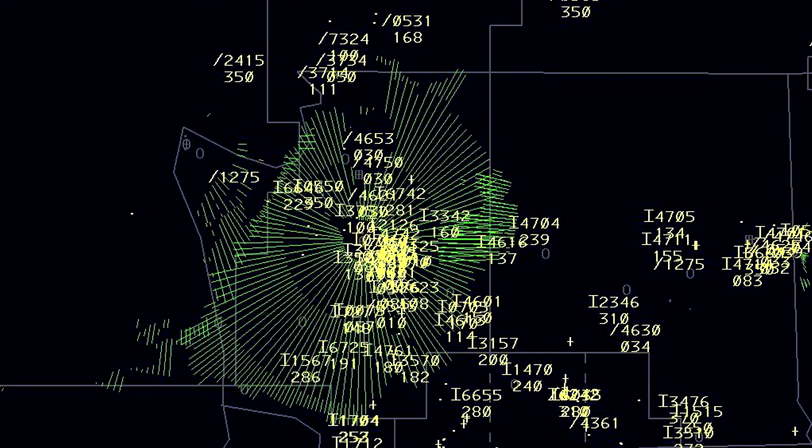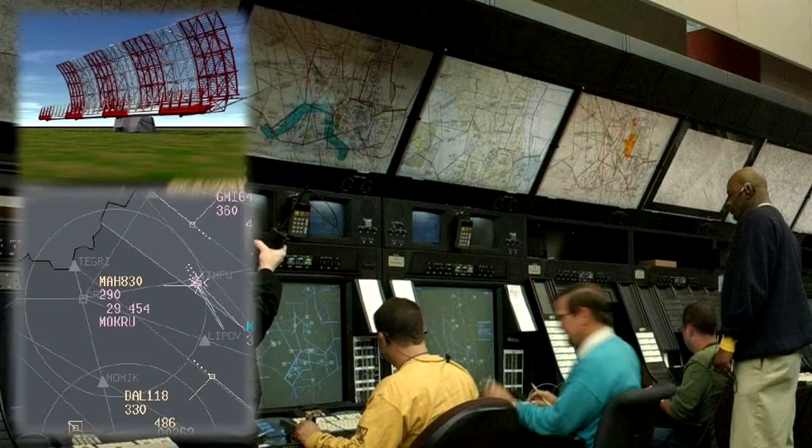Today, the use of radar, with the addition of computer-enhanced systems, is a completely integrated part of the control of air traffic. Before we look at radar technology in more detail, it is important to understand that an air traffic control radar system is not just a visible rotating dish seen near airports. A radar system will normally consist of a number of integrated systems, including radar sensors, radar data transmission lines, radar data processing units, and of course the radar data display.